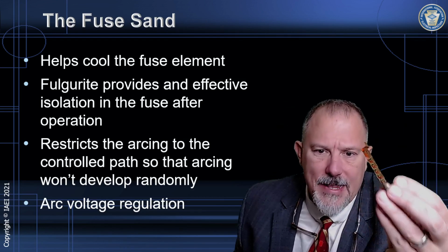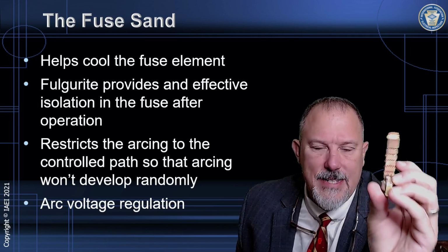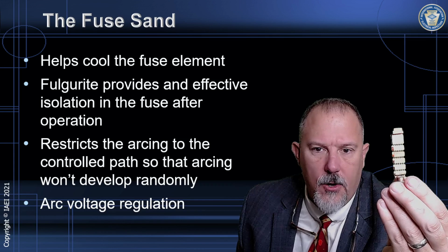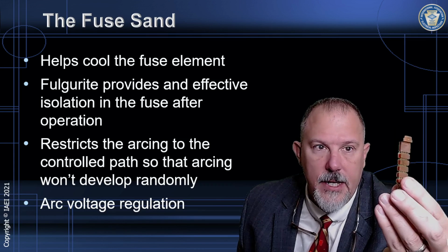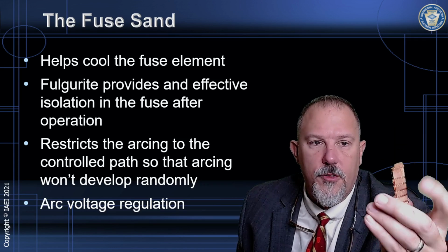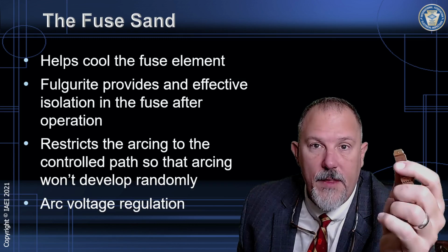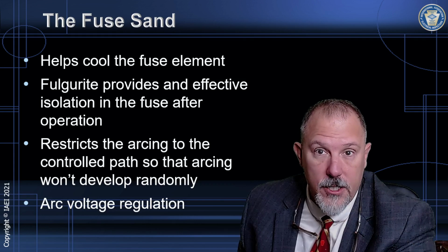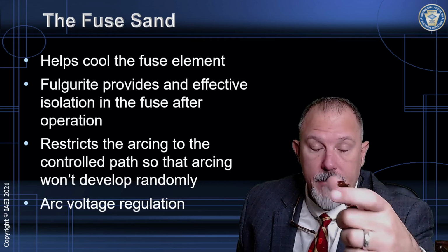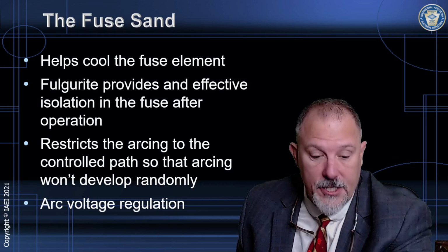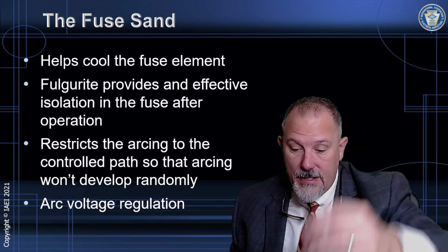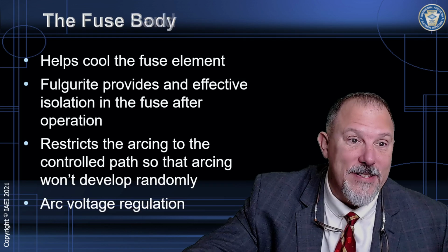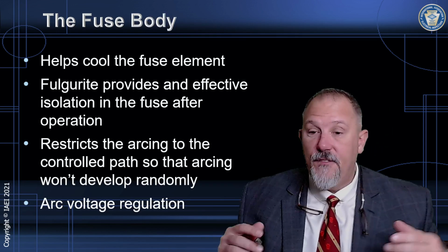So think about this element surrounded in sand, and every one of those pinch points is covered with sand. The current will flow through these tiny pinch points, but when they open, that sand is there to help absorb the heat, contain the arc, and facilitate the isolation. Now I'm going to put this right in front of me so I don't forget where it's at. Now the fuse body.